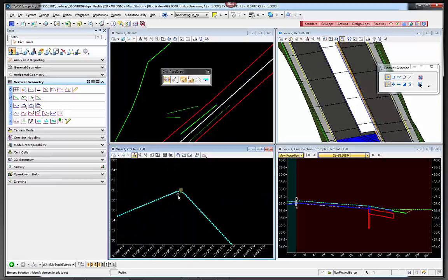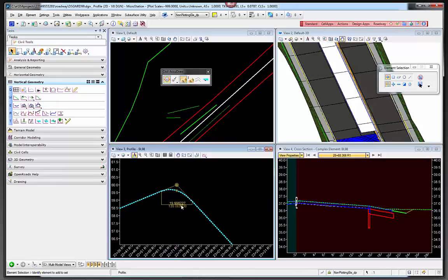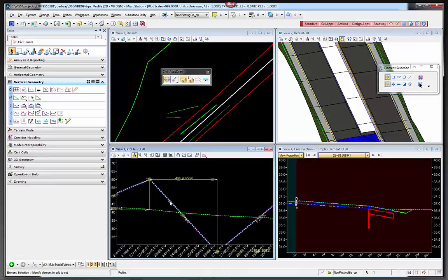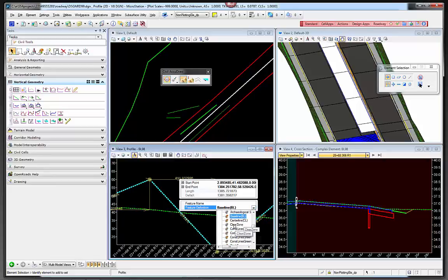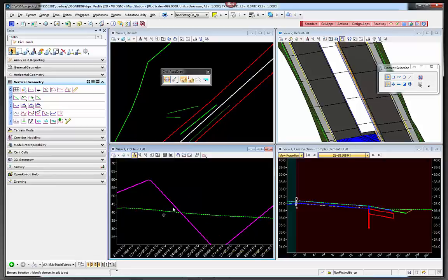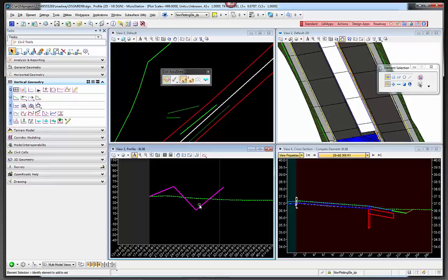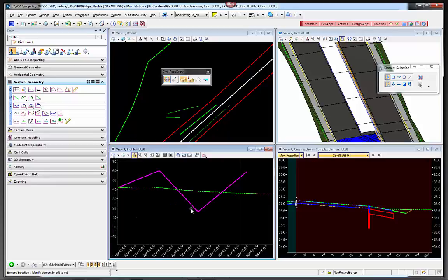And if you want to change this curve parameter, if you pick on the curve, you can actually change the values, either the curve parameter or the actual length after it's been placed. So if you want this to really be 25 feet curve length, of course this feature is not correct. You can change the feature anytime. Just use a centerline feature. And now it's normal. So there's lots of ways of using Civil AccuDraw.